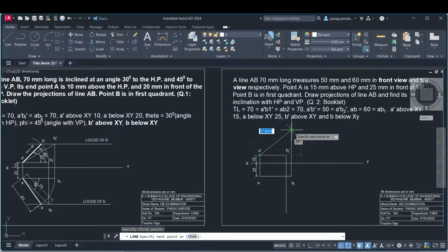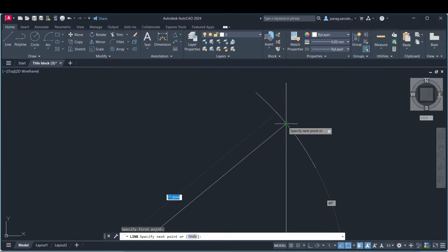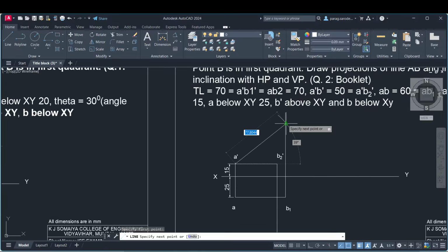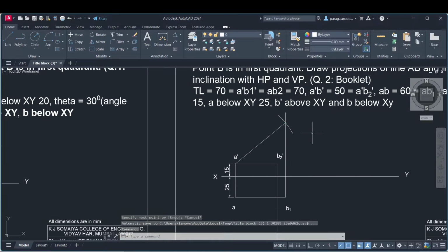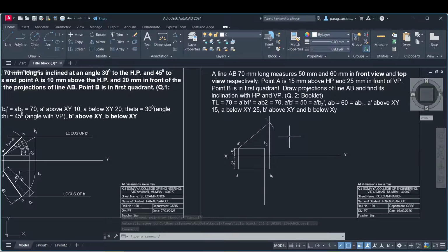Make sure while joining, take proper care so that we snap to the intersection instead of this midpoint. There will be a very small gap between the midpoint and the intersection. Can you use a circle instead of an arc? Yes, if the line is visible, definitely you can use a circle. If the line is not visible, it's fine. I will show you how to use a circle.